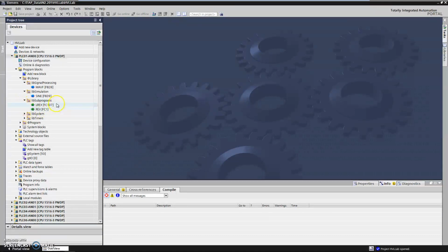And here are some subprograms. The Siemens PLC doesn't have any exception processing calls, so we can check if, for instance, a multiplication goes right or wrong with a floating point number. So here is a function that can check if a long real number is legal, and this one can check if a real number, a short real number, or 32-bit real number is legal. So this is a real number exception.